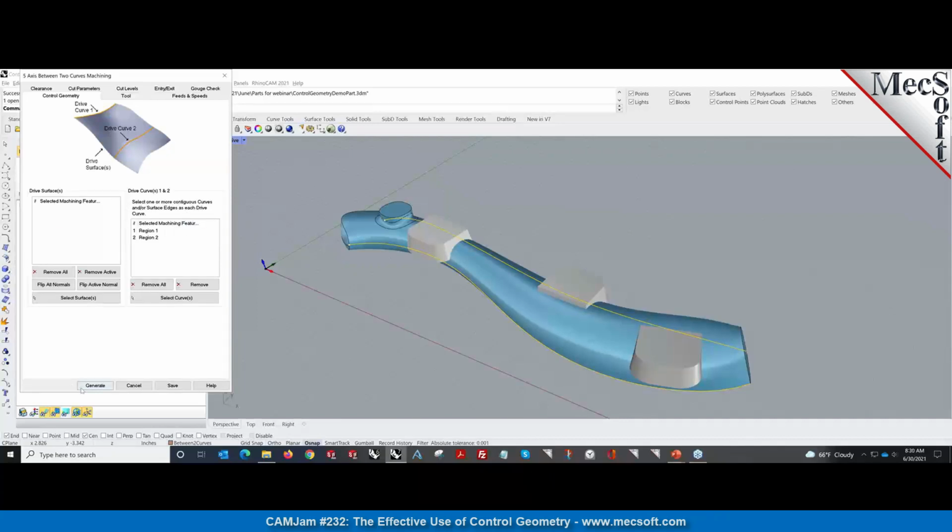The drive surface in 5-axis mode, as compared to 3-axis mode, has two things associated with the cut pattern. In 3-axis, when you said parallel finishing, you would basically take parallel planes along the X or the Y axis or any angle axis, and then slice the model, and wherever the model is sliced is where you're cutting. You can think of it that way.